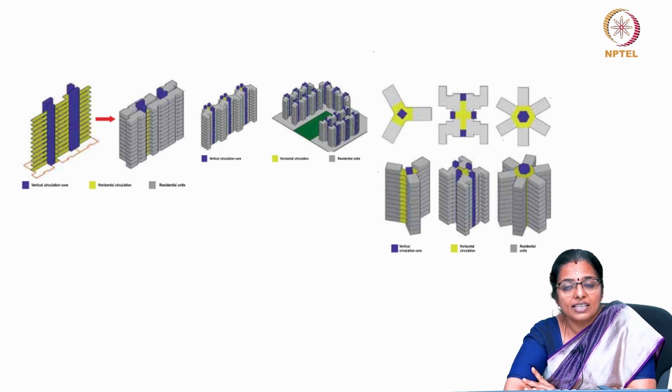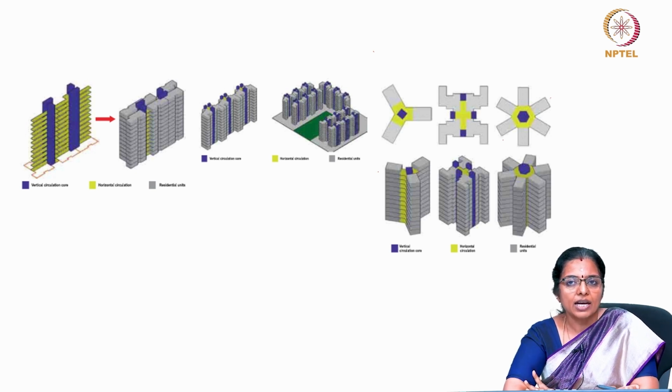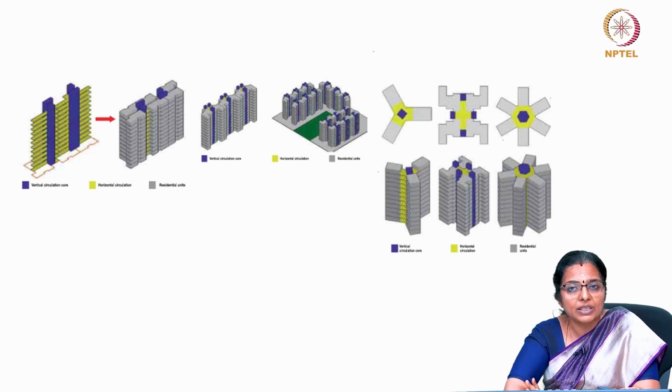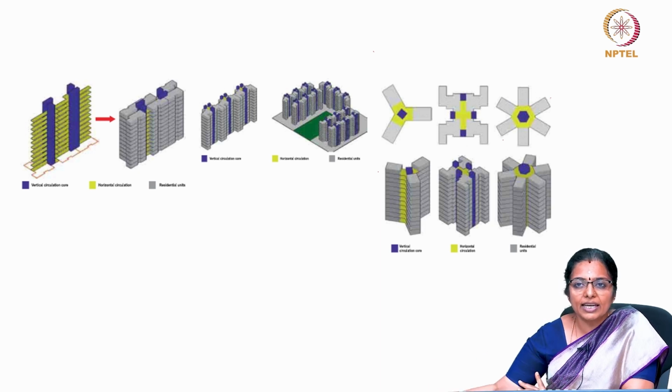In the last class, we had seen how they can be made to shade each other, and this slide is also a reminiscence of where we left. Building blocks should be arranged so as to benefit from mutual shading, to minimize solar exposure on the vertical surfaces during summer months, and we should look at mutual shading in greater detail.